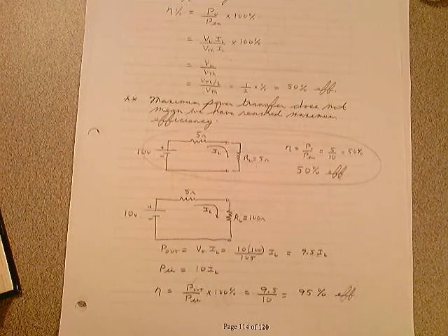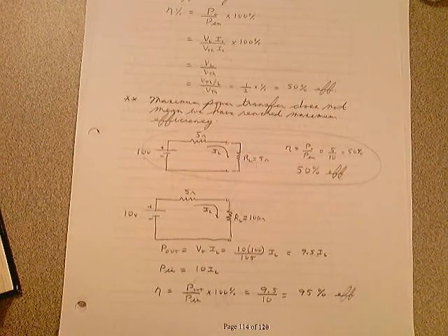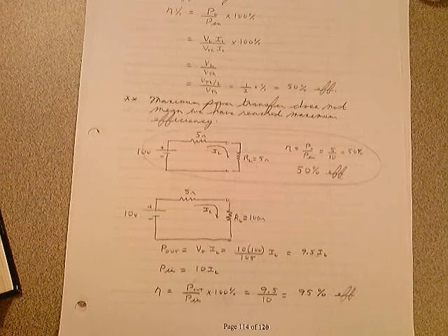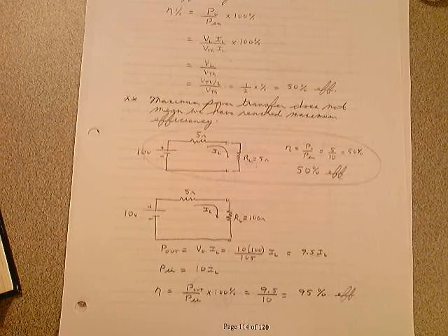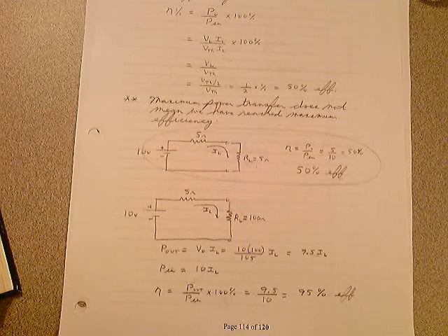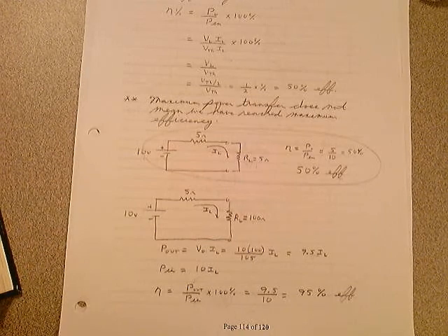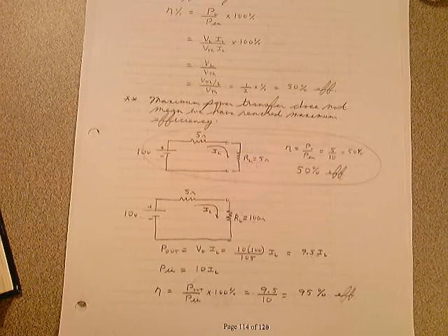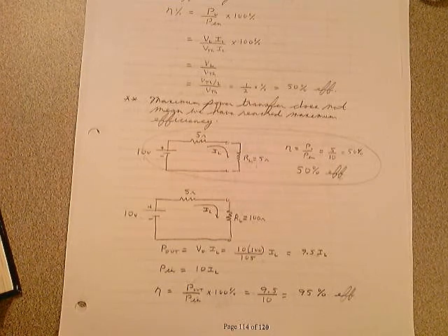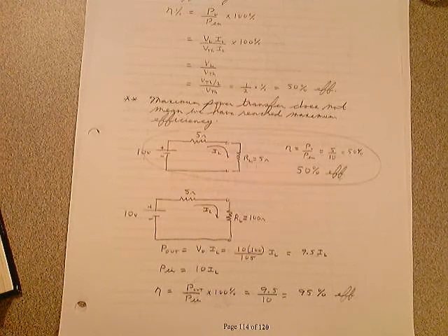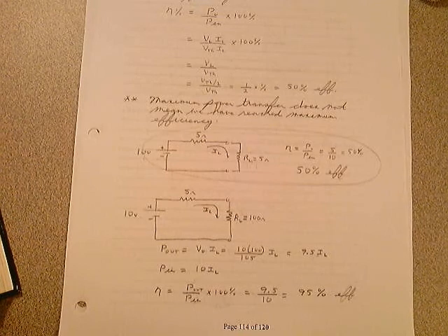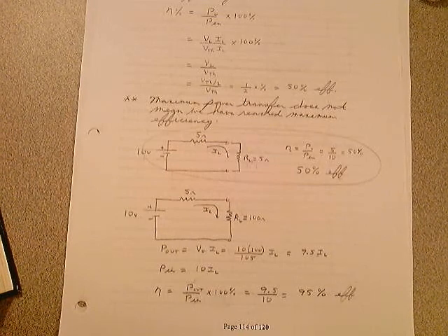You want maximum voltage? You want maximum power? You're going to want maximum power efficiency. You match those speakers to the output resistance of those power transistors or those power circuits. Essentially, that output impedance or output resistance is, in effect, Thevenin's resistance or Thevenin's impedance.